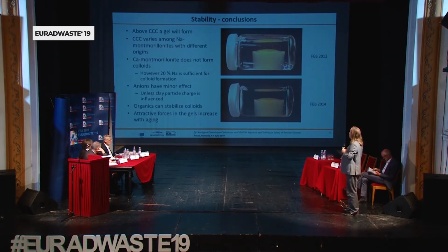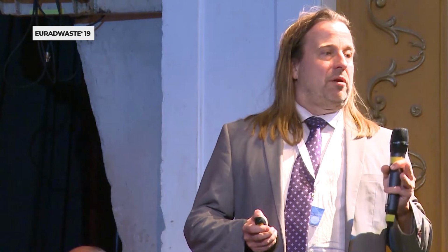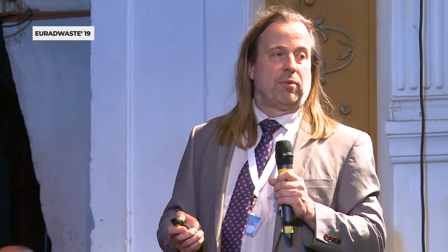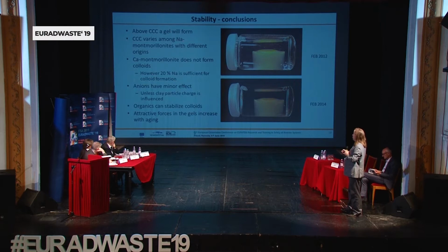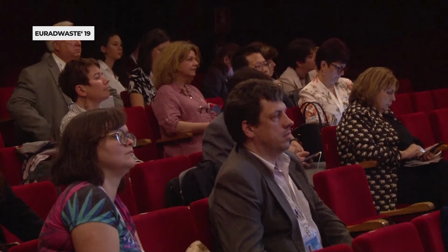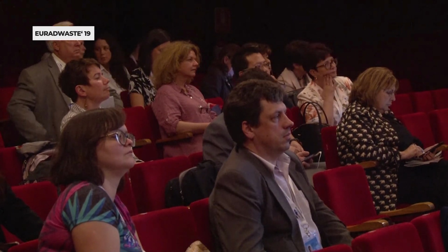Stability above a critical coagulation concentration, which is maybe 4 millimolar sodium chloride for a mixed clay, sodium calcium, and 25 millimolar for a pure sodium clay. You form a gel and no colloids are generated. This CCC varies among sodium montmorillonites of different origins. Calcium montmorillonite does not form colloids. However, only 20% sodium is sufficient to basically turn a calcium bentonite into a sodium bentonite in this respect.